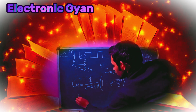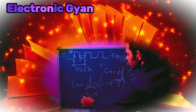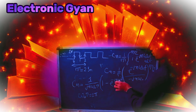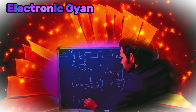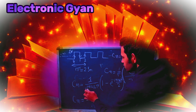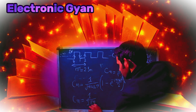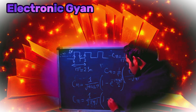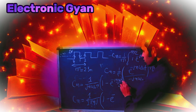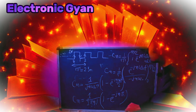As we know very well, omega naught T is equal to 2 pi. Just put omega naught T equal to 2 pi here. We get Cn equal to 1 by, jn omega naught T is 2 pi, so this is 2 pi n j, and this is 1 minus e to the power, when we put omega naught T equal to 2 pi, the 2 gets cancelled and we are left with jn pi. So this is the Fourier series expression.